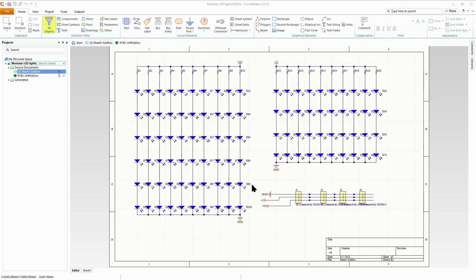And then we've got power connectors. All the LEDs and resistors are all surface mount devices, whereas these board connectors are through-hole devices. Whether or not you use these actual connectors is kind of irrelevant. The fact of putting them on the board gives you the through holes that you can then just wire directly to if you want to, or you can use these terminal blocks for powering it.